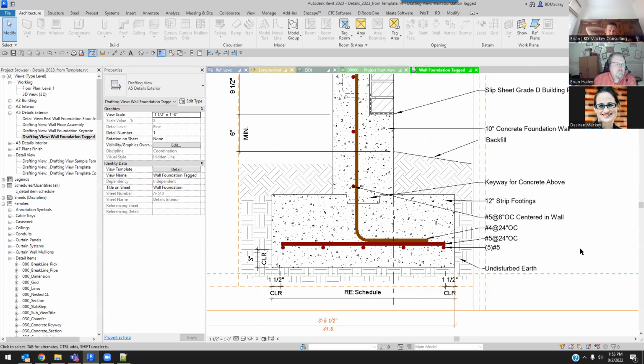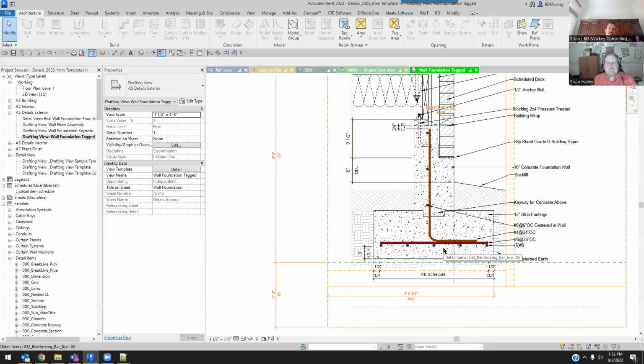Yeah, I did also do the details at Revit Pure too. So like I said, you guys are starting out from CAD. You're going to be bringing in some CAD details and using those in your first few projects, because you can't stop and do everything else to just do details. But it's always, like I say, you bring a detail in, like, oh man, I need to tweak this. That's when you should take that typical detail and start using all Revit components. Oh, this detail needed a change. I'm going to change it by converting it to real live Revit components, not just exploding it and changing the lines.